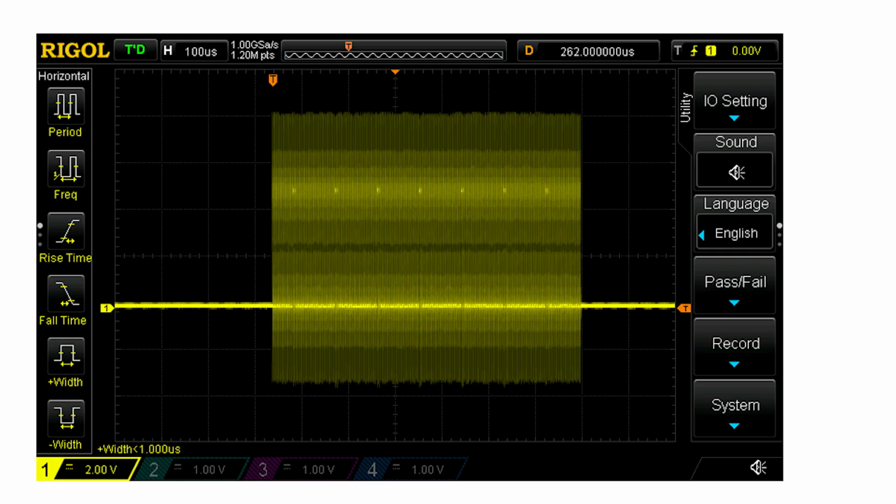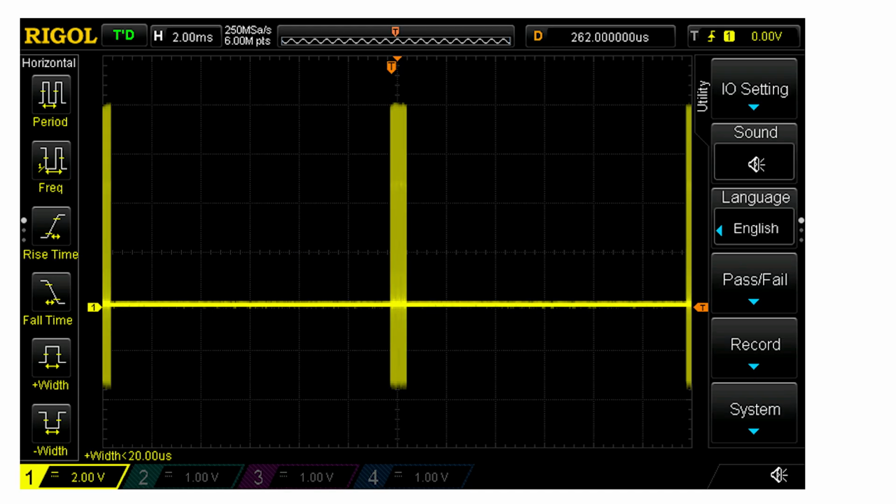That there is 25, I think, NeoPixels in a chain. And that happens in less than a quarter of a millisecond. That pulse for 25 of these is a quarter of a millisecond. And if I zoom out on my scope, you see there's the quarter of a millisecond, and it's every 12 milliseconds.